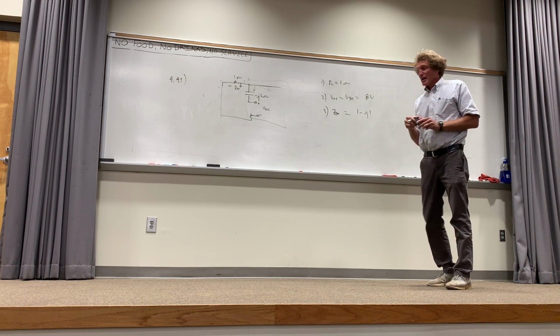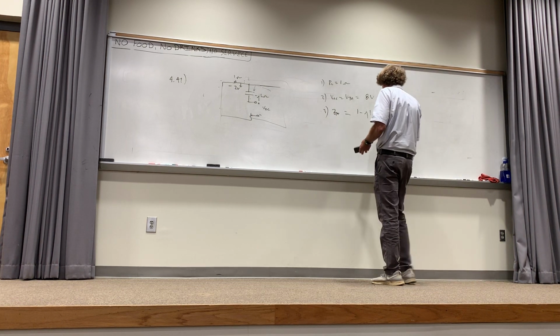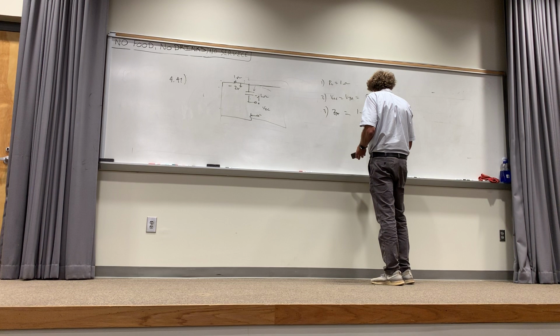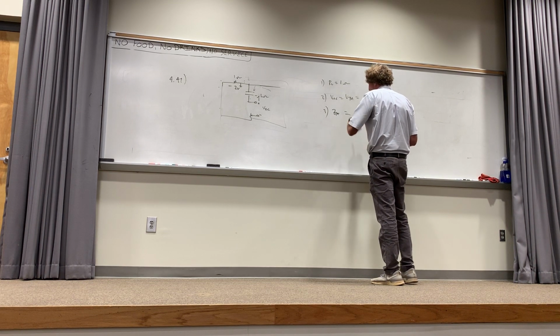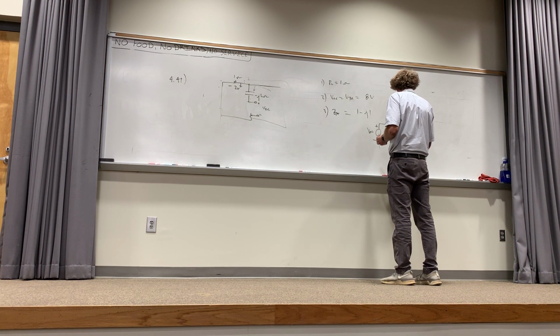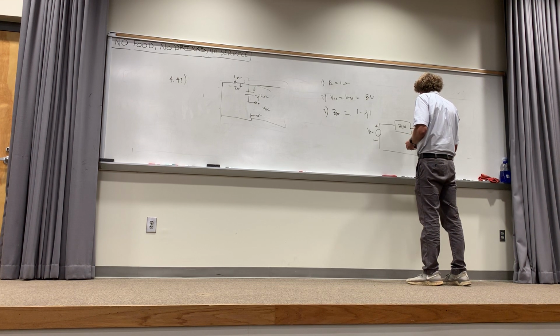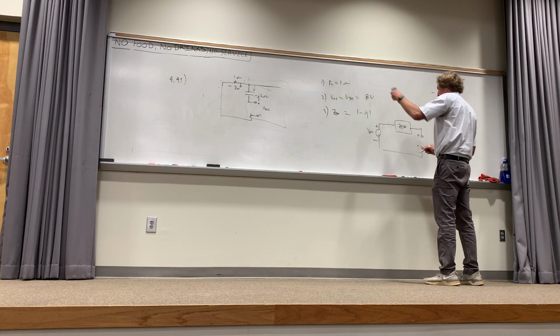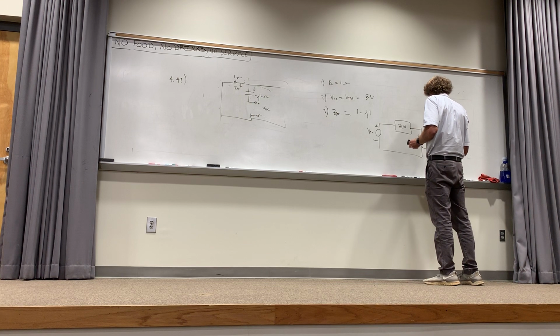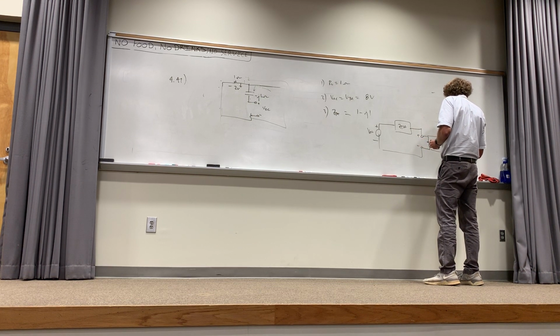You plug back in. Now you've got to build a circuit, right? You start by putting the open circuit voltage here, plus or minus VOC, which we have. Then you put in the net impedance Z Thevenin right here, right? And I'll put it in a second. Then you come down here, and now you reinsert the load, which was 1 ohm, right? And they wanted this voltage, so this is actually what I'm after, that voltage.